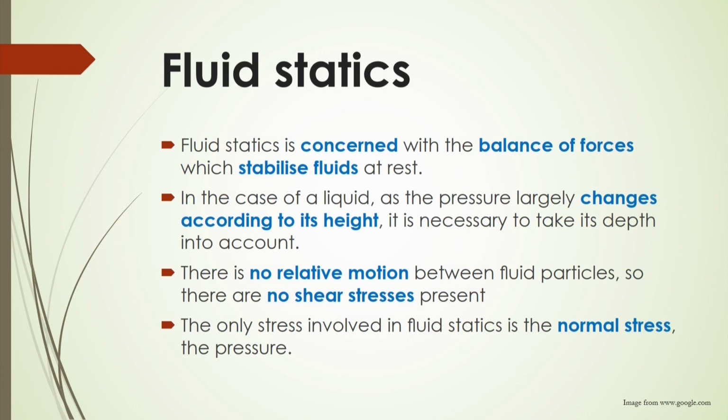In fluid statics, the fluid is at rest, so there is no relative motion between the fluid particles. That is why we can consider that the fluid has no shear stress in this condition, and the only stress involved in fluid statics is the normal stress, which is called pressure.